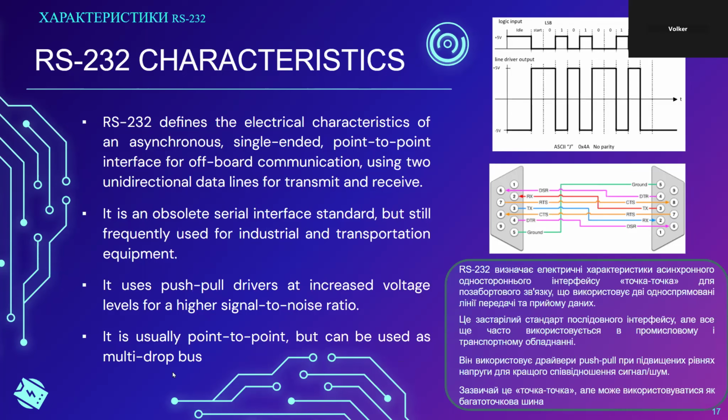So RS-232 was designed at a time when differential drivers were not possible easily in hardware. Transistors had just been invented, and were becoming common, but really they were trying to increase the signal-to-noise ratio of a single-ended communication line that was supposed to go off-board.